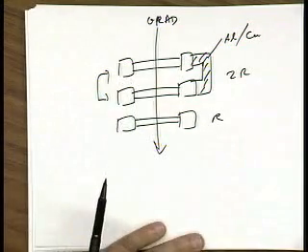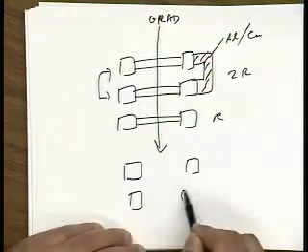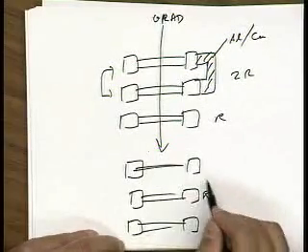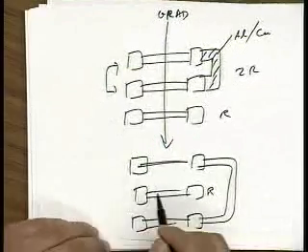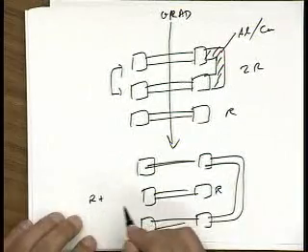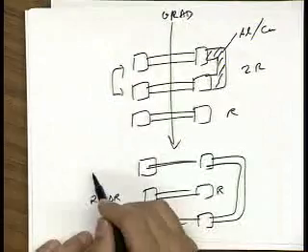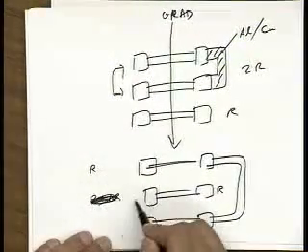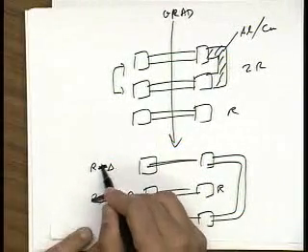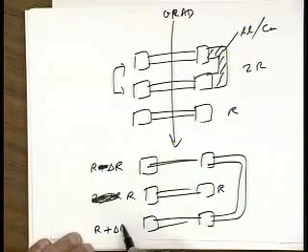Yes, to interleave the resistors. Yeah, interleaving. So what if I put my unit element R in the middle and then now connect like that? How does that take care of the problem? Well, let's say this is R plus delta R. Because of the same doping variation, let's just call this R, make things simple. Let's say this one is doped a little bit higher, so it's R minus delta R, and this is doped a little bit lower, so it's R plus delta R.